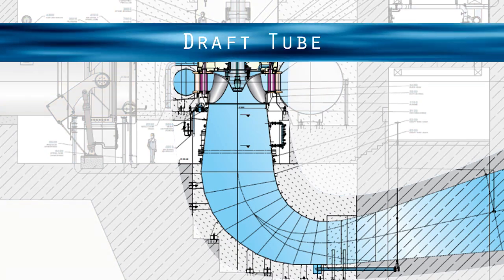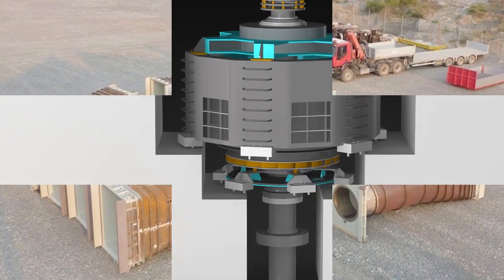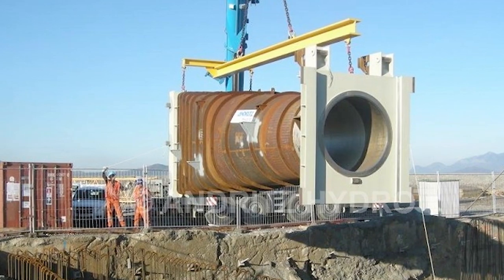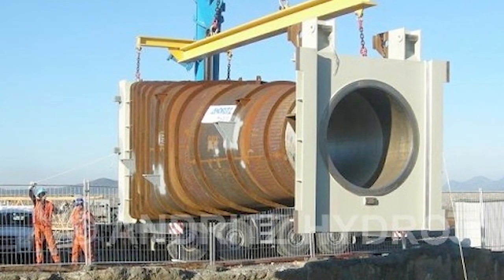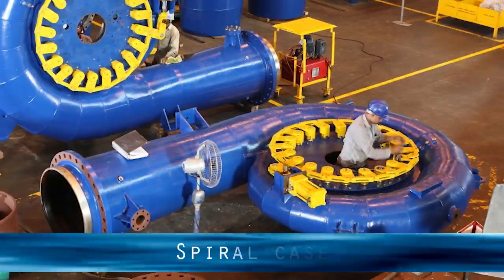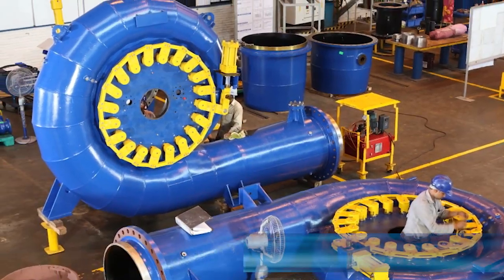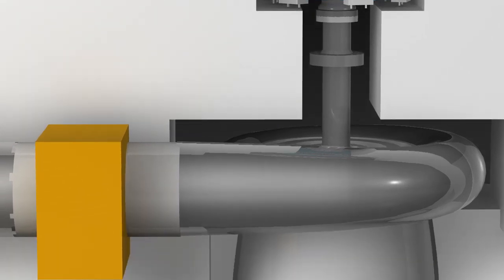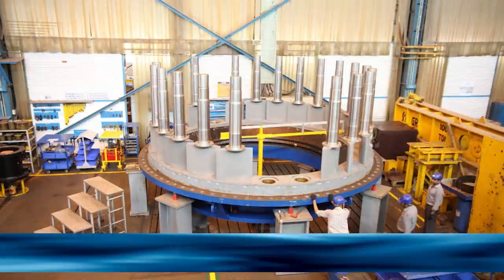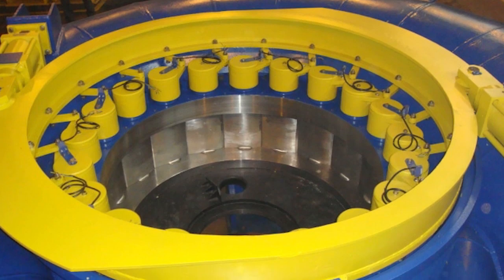Draft tube. Draft tube conveys the water from the discharge side of the turbine to the tail race. It is designed to minimize exit losses. Without a draft tube, pressure could drop, causing turbine failure. Spiral case and wicket gates. This is a steel-lined conduit used to direct and uniformly distribute the water into the turbine runner. Wicket gates are adjustable vanes surrounding the turbine runner to control flow of water into the turbine.